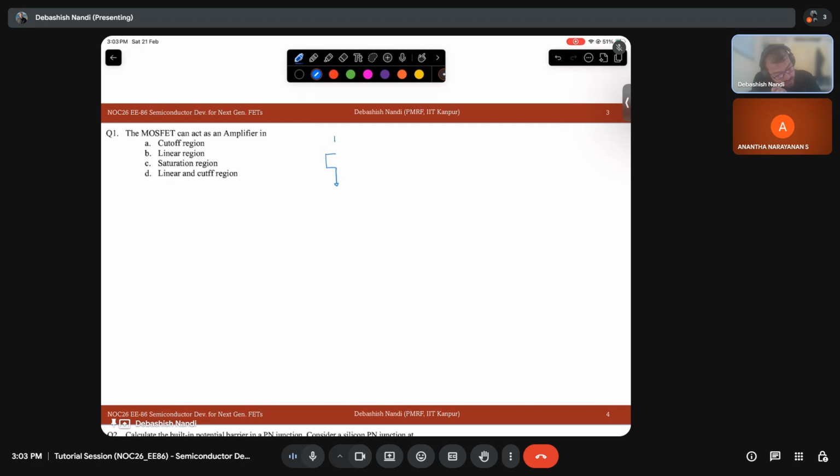I draw a MOSFET. Let's take an NMOS. So this is gate, source. Let's say body is shorted to source, and this is your drain. So what are the first things? First, you need to bias this, right? Then you will be biasing this, let's say at some VDD, or let's add some resistance, and this is, let's say, VD. Let's say this is VG.